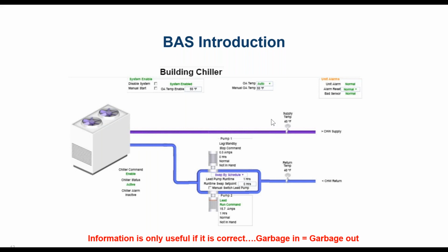So that's where a lot of my experience comes from when it comes to building automation systems, kind of checking out other people's work. But additionally, as you move into the operating phase of a facility, you got to make sure that as sensors fail or become uncalibrated, they get replaced or get calibrated.